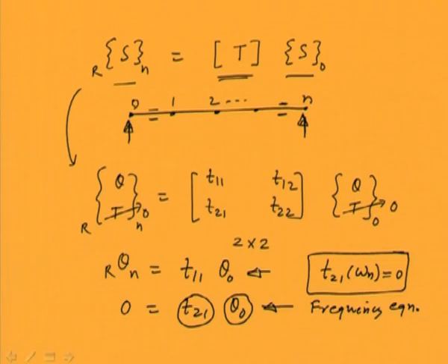This second equation will be used to obtain the mode shape. So once we have solved this particular frequency equation, depending upon the number of degrees of freedom in the system, that means the number of disks in the system, we will have that many natural frequencies. Like if we have n number of disks in the system, rigid disks with the massless shaft, we will have n number of natural frequencies, and so here